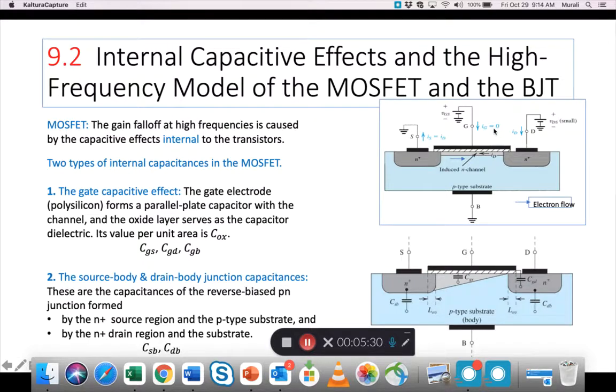So this is an image from previously where we used this to understand how the MOSFET works, right? And first we are talking about the MOSFET, then we look at the BJT. So we know that the MOSFET construction looks like this. An NMOS MOSFET is what you see here. There is a P-type substrate in blue. Then there are two wells.